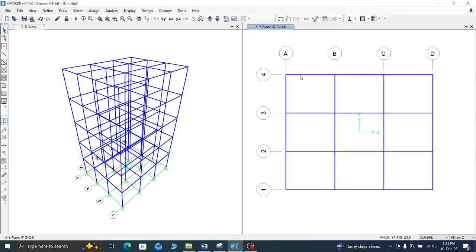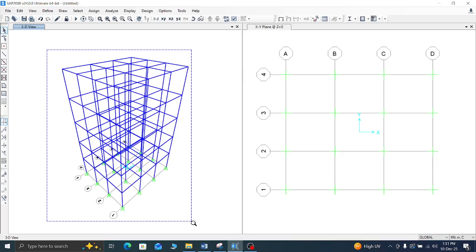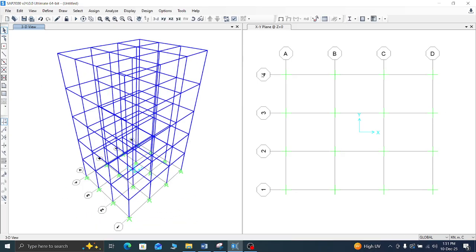So the direction also, this way you can choose X, Y, Z and 3D. If you want 3D here as well, you can click this. I am just keeping this one at the ground floor level. After doing this, what I am going to do is the basic things. If you want to fit this into the screen, you can use the rubber band zoom option, and you can click this one, so it will best fit to your window. Here the display is best fit.